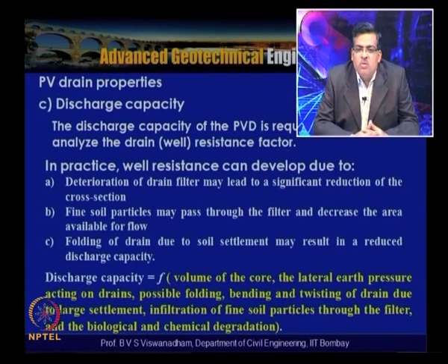So, we may have to note that the PVDs are flexible in nature, and the soil is subjected to settlements. The PVDs are affected due to two reasons. One is that the soil is subjected to settlements because of the onset of consolidation, and the second is that due to the presence of the lateral pressure, the drains are subjected to so-called buckling. That means that they can undergo buckling at one location, two locations and three locations. So, even under those buckled conditions, it should be able to satisfy the required discharge capacity requirements.